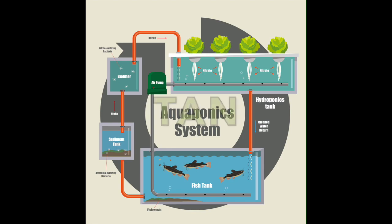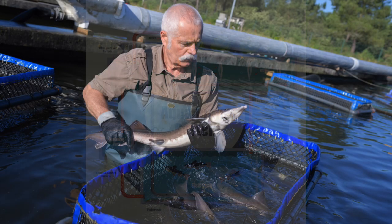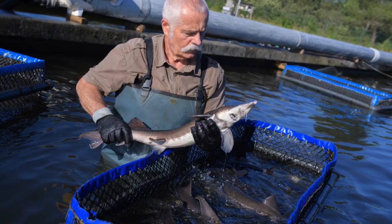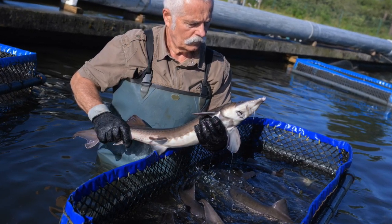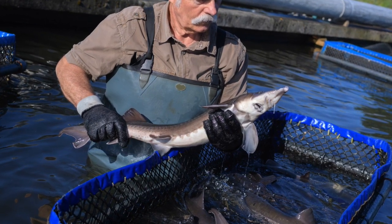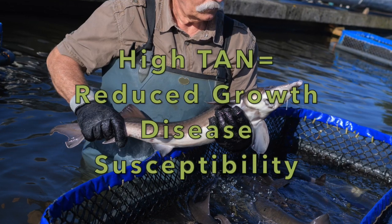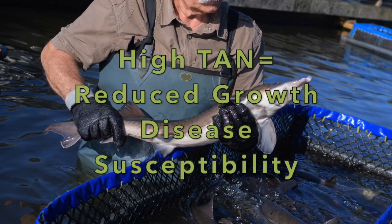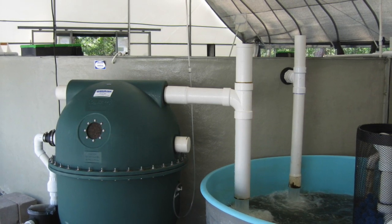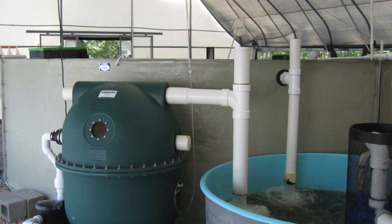Total ammonia nitrogen, or TAN, is determined using analytical methods. The amount of TAN in ionized or unionized forms varies with temperature and pH. As pH and temperature increase, the amount of TAN in toxic unionized forms increases. Fish that are continuously exposed to unionized TAN at levels greater than 0.02 ppm may show reduced growth and increased susceptibility to disease. Ammonia and other metabolic wastes are gradually removed from water by natural processes or by biological filters in recirculating water systems.